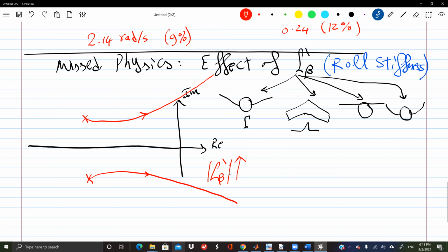So what do you think? What do you get from this sketch? Large magnitude L beta will give you an unstable system. Exactly, right? Because after a while, these will cross the imaginary axis, and the system, what system? We're talking about the Dutch roll mode, which is an annoying mode. It's a relatively fast mode. If it becomes unstable, then this will be quite dangerous.